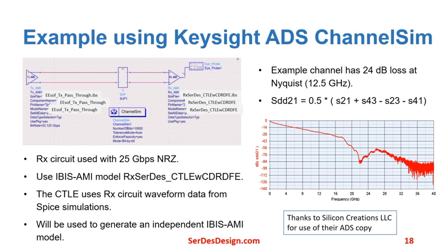We're going to discuss an example using the ADS channel simulator. In this ADS schematic, the Rx IBIS-AMI model is set up using the SerDesDesign.com Rx SerDes_CTLE_CDR_DFE model. This is a behavioral model that uses Rx circuit waveform CTLE data obtained from SPICE simulations along with the CDR and DFE models. The model will be used to generate an independent IBIS-AMI model.